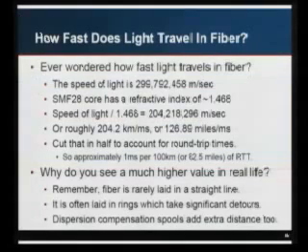Other miscellaneous fiber information. I have people ask me, how fast does light travel through fiber? If you want to do the calculation, the speed of light is about 300 million meters per second. SMF-28 core has a refractive index of 1.468, so you take the speed of light, divide it by the refractive index, and now you get the speed that the light travels in fiber.